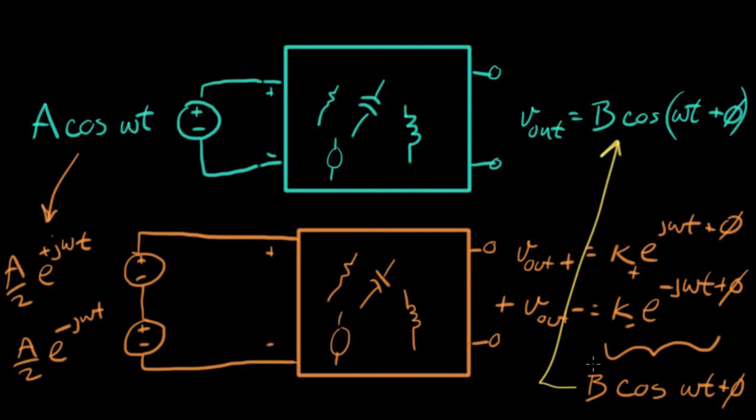So just so you know it's not twice as much work, it's going to turn out that this whole solution down here using the negative exponential, the answer is going to be exactly the same as the positive exponential, except there's just this complex conjugate in here. So for real signals going in, these answers are always complex conjugates of each other, as long as we start with a real input.